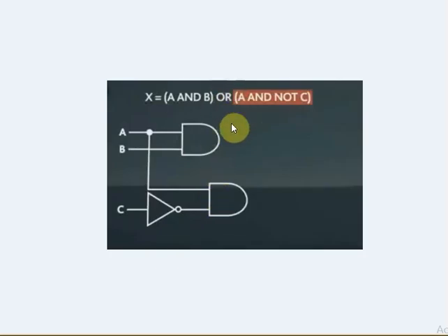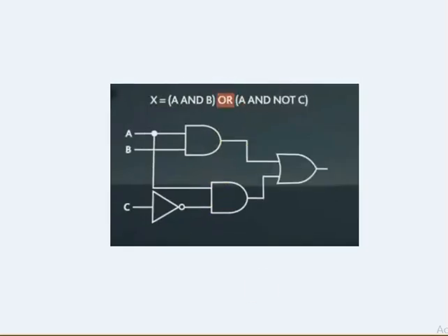Now the OR gate. Put OR here. It's very simple, no? With the OR itself, you know this is one branch, this is one branch. Otherwise, if you are starting from one side, you can start from here, then you can put the other branch, and then you can see whether it is an AND gate or OR gate, you can implement here. Therefore, now you should get very familiar, right? Even the Boolean expression to logic gate to Boolean expression, truth table, everything.